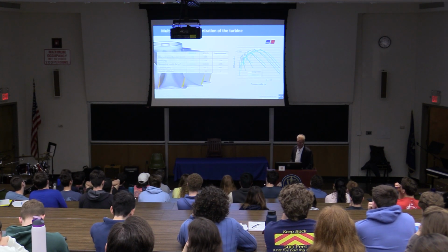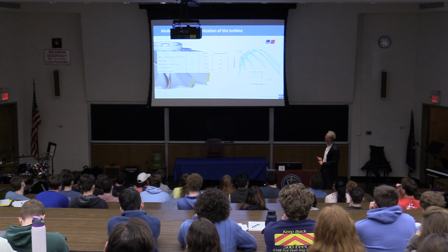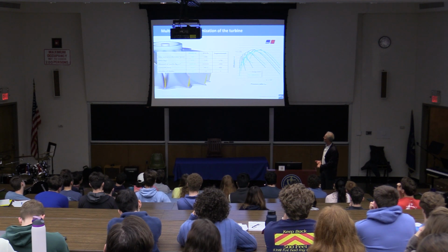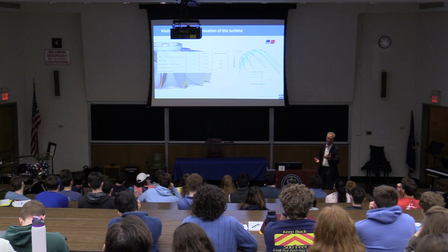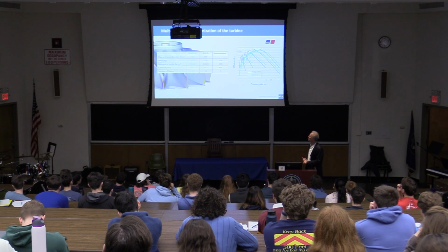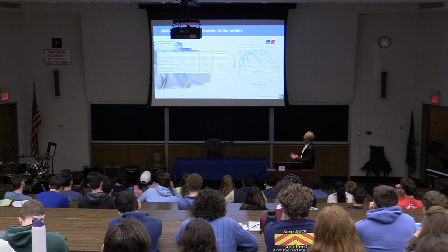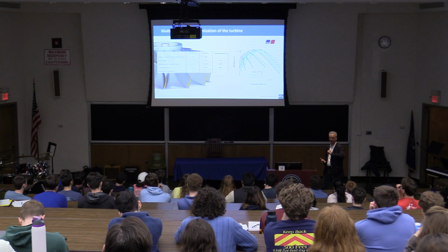And a direct comparison then shows, for the same diameter, because otherwise you would compare apples and bananas, you have a little less mass, 70%. That per se is nice, because you spend less material, but it's not changing the situation too dramatically. You have less moment of inertia, 24%, so the turbocharger is running up much faster.